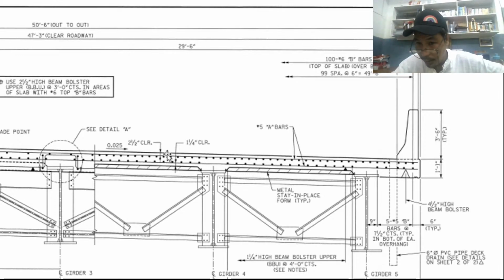So we are using 40 mm in our country as a concrete cover. So these are specific dimensions. You can memorize that 40 mm for concrete cover. That is specific dimension. That is not guesswork. That is specified and planned. Okay, so 40 mm top concrete cover.